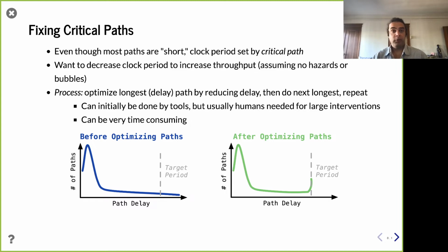Now, what's interesting is if you go out, measure all those various paths in the design, and actually traverse all those possible paths in that combinational explosion, what you're going to find is that most paths aren't near the critical path in terms of delay, right? The critical path is going to be an outlier in some ways. And even though it's an outlier, it's still going to limit your design, right? So you really want to narrow your distribution in a way.